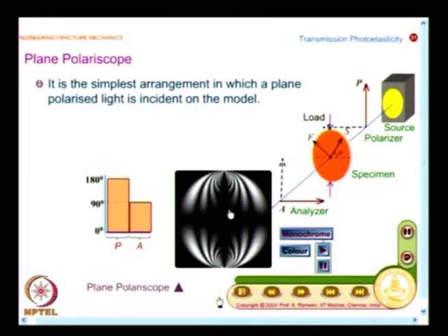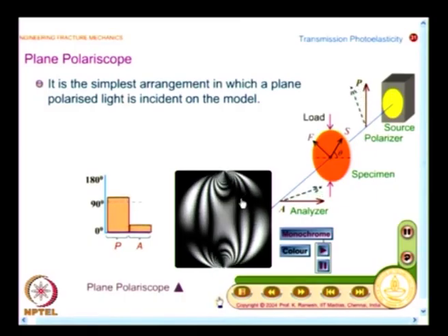We have also looked at that if I increase the load, the stationary contours will move because they are an effect of the load applied. From the principles of solid mechanics in linear elasticity, the principal stress directions do not change, only the magnitudes. You have tan 2 theta equal to 2 tau xy divided by sigma x minus sigma y. When the loads are increased, the individual magnitudes of shear stress and normal stress vary, but theta as such will remain constant.